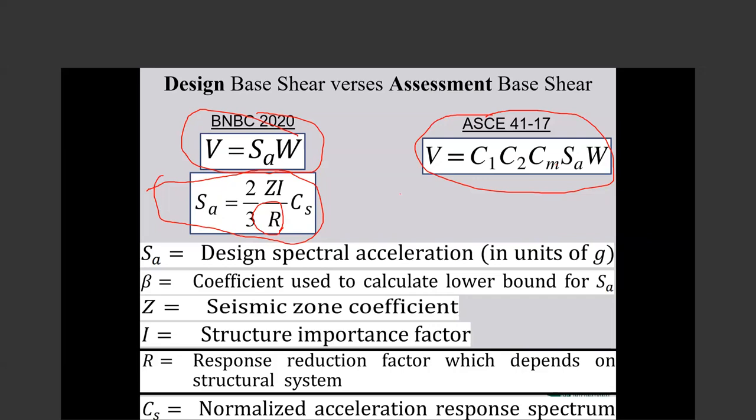We call it the M value. What is the M value of this element? This element, oh, good detailing. The M is high, is 10. Oh, the other beam is very bad detailing. M is 2. The other one, M is 3. So it's very difficult. Very difficult. Time consuming. But the main purpose of the systematic retrofitting and evaluation is to be financially as low as possible.